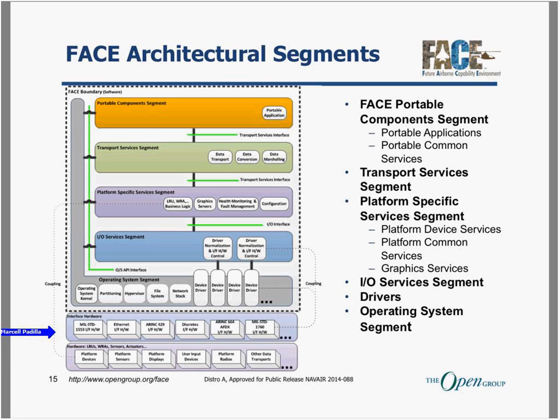Next is interface hardware. When we talk about interface hardware, the examples are listed in there: MIL-STD-1553 bus, Ethernet, ARINC 429, discrete, the way that we're going to transmit data across hardware boundaries. Both of these things operate in non-standard ways and typically output data in non-standard ways, whether the data from the sensors or effectors is proprietary in nature, or the implementation of the standard interface hardware is not exactly the same.